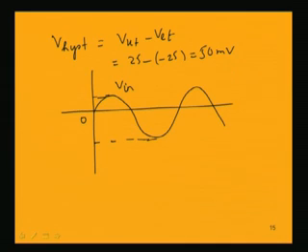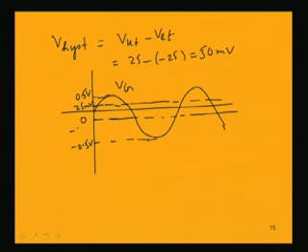So, obviously this V peak will be 0.5 volt and this will be minus 0.5 volt for the input voltage, and the upper threshold and the lower threshold voltages are 25 and minus 25 millivolt. It is not to scale, I am just showing to illustrate this example. Suppose this is VUT, this is VLT.